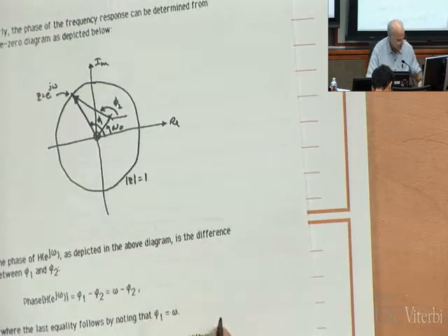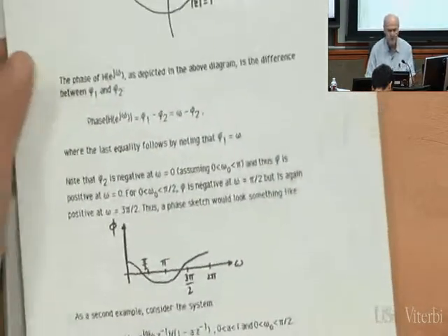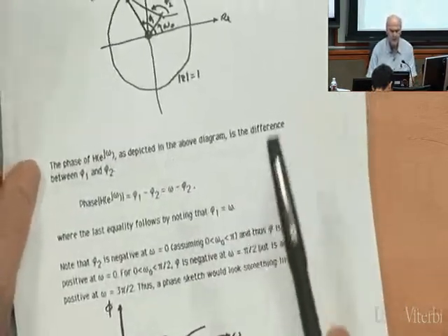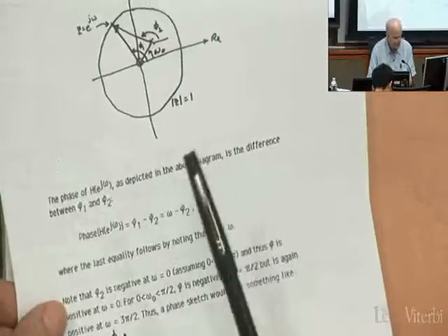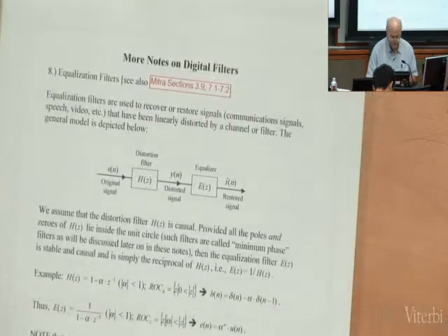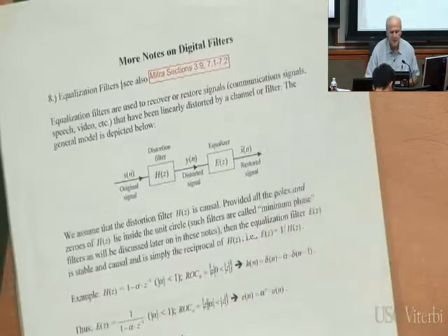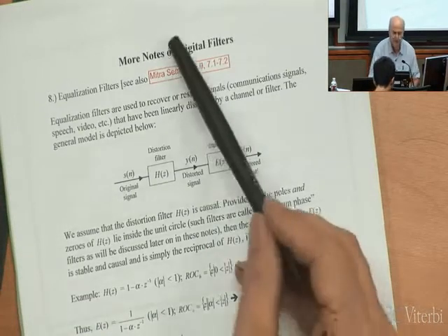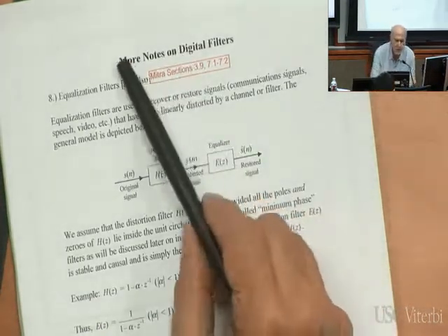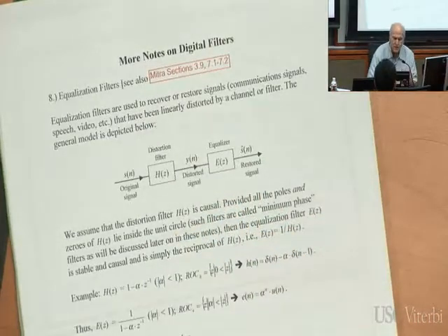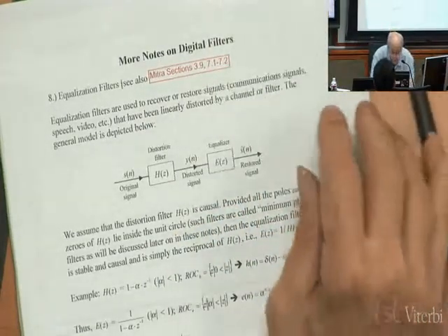So that is the story. I even discuss a little bit, and give you another example, and I also discuss the phase response, so you might want to take a look at this. It's kind of interesting. Okay, now I have another example. I will talk about this after the break, but it is a very interesting example where we try to approximate a non-causal filter with a causal filter.